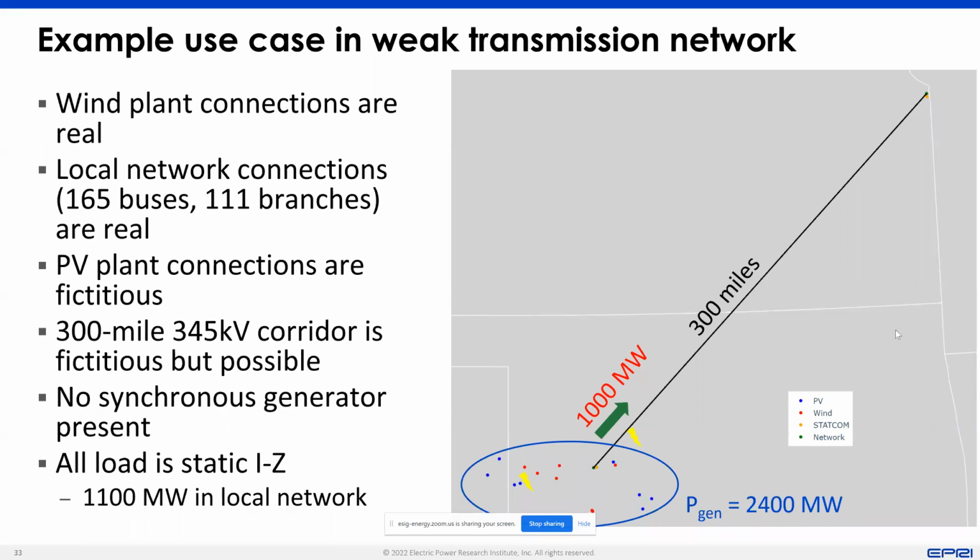If you have a battery, some inverters have the capability to have an update to change from grid following to grid forming, provided you have the same limitation on maximum current, the same limitation on that kind of capability curve envelope. But it depends upon them having the capability to do it.